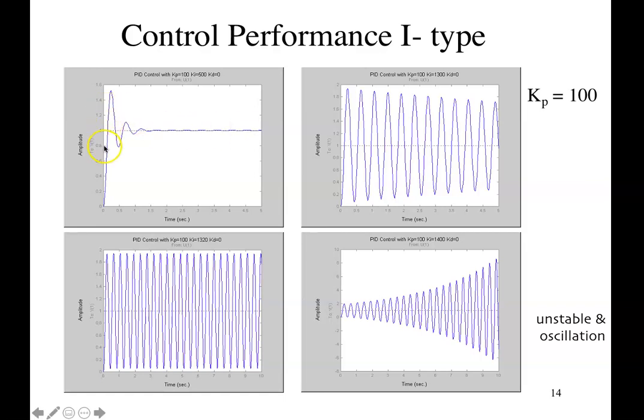But if you look at overshoot, there's quite a bit of overshoot. Okay, so it has the effect of increased overshoot. But if you're not careful, you get the control gain too large. In this case, control gain is 1300. Now you see oscillations. The amplitude of the sine waves gradually reduces, but it takes a very, very long time. If you see the trend, if I run the system further, it probably takes quite a while for that sine wave to die down.